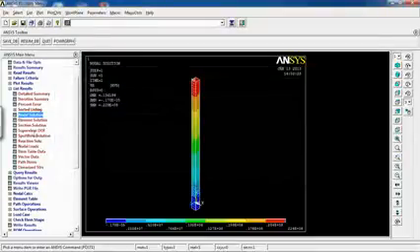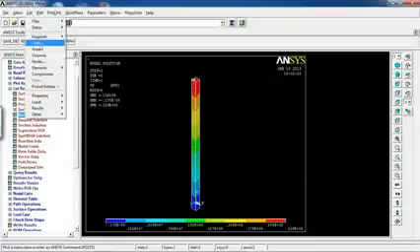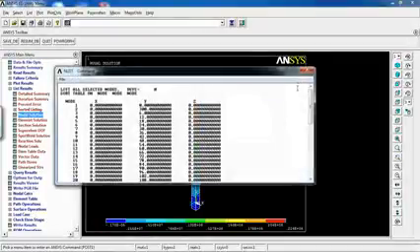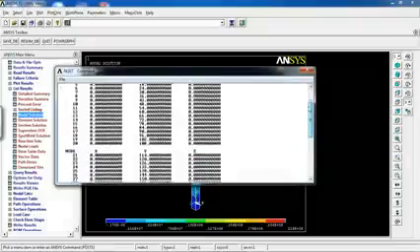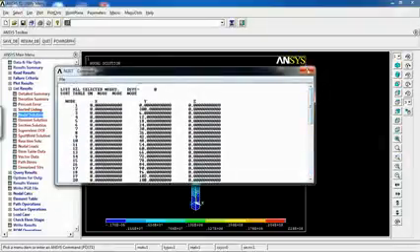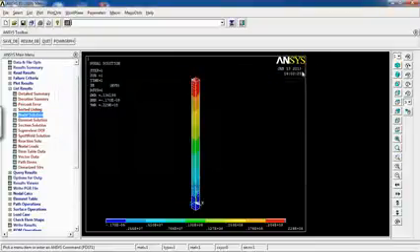So I can read those displacements from here, and list nodes, coordinates only. Okay, so I can read these values from here, save the two files, and merge them together and get one single Excel file and plot y versus displacement in y direction in Excel. With this, I'm going to conclude lesson 7.